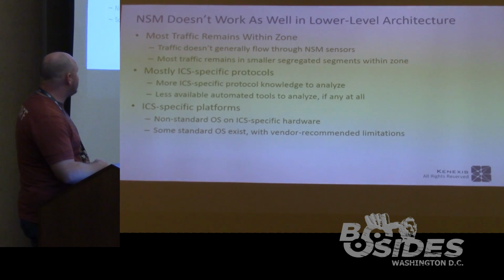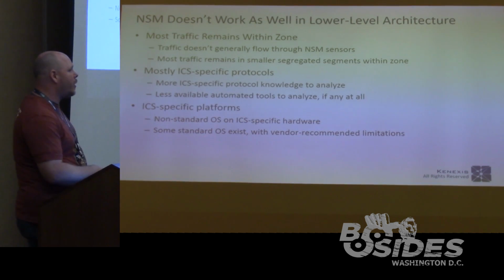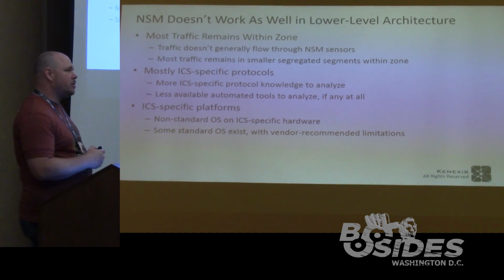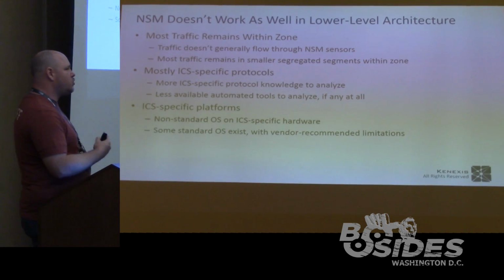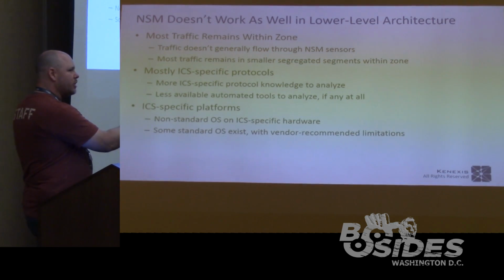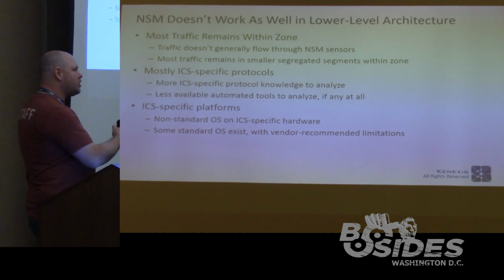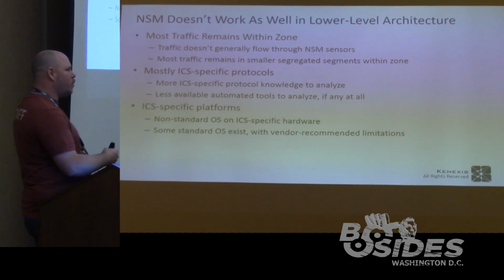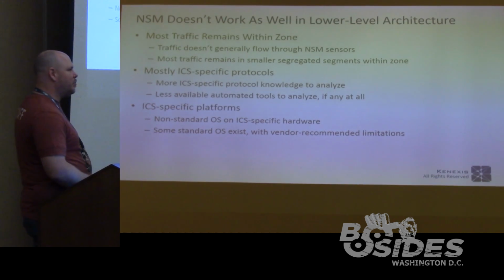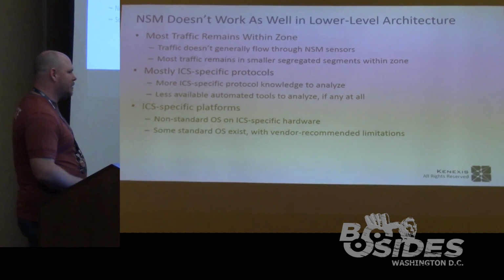Even when you have standard OSs in your systems, you can't always trust that the vendor will allow you to install something on there, because they've locked it down as a warranty matter: we won't service this if you install antivirus on it, because antivirus slows it down to the point where you've lost your determinism.